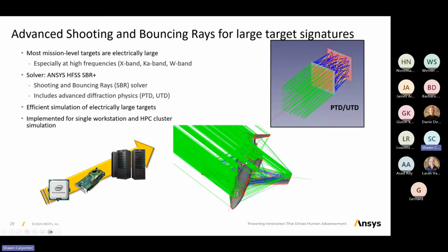You can see here in one case with a plane wave excitation here, all of the rays that we're taking into account as we compute these signatures. And let me just mention here, when we do ray tracing, we don't trace rays from source all the way through to an observation destination. We trace a huge number of rays to find the interaction of a local body or scatterer, and we use those rays to plant what's called physical optic currents, localized current patches that match Maxwell's equations for the reflection of a wave at that localized area.